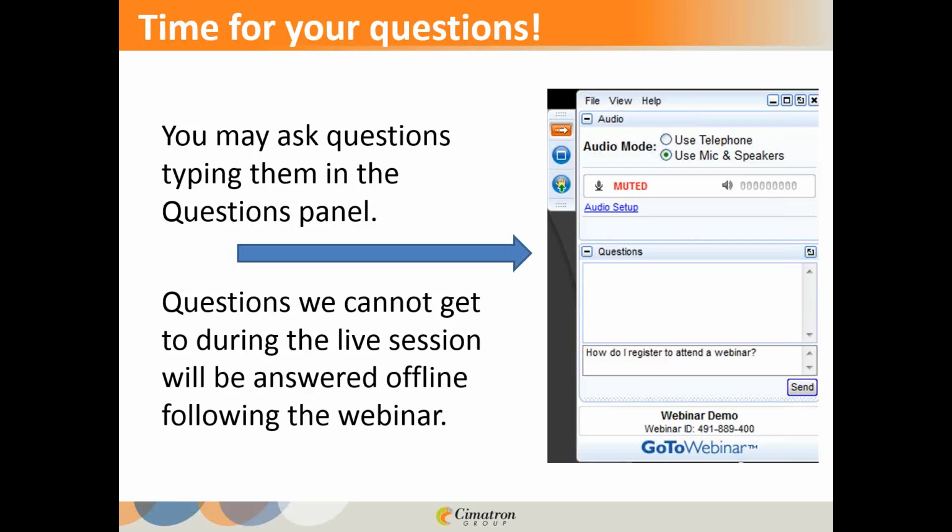Right. A couple guys asked kind of the same question. Can you account for process variables, forming speed, for example? Yeah, that's a good one. With a deep draw part, the slower you get, the easier the metal is to move. You're not likely to shear it so bad, that kind of thing. Right, and you're going to generate less heat. Right, less heat. That part of predictive intelligence, I would say we do not have. Okay. We can't do that yet.